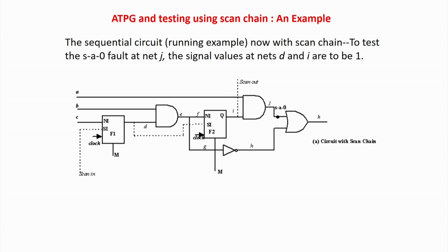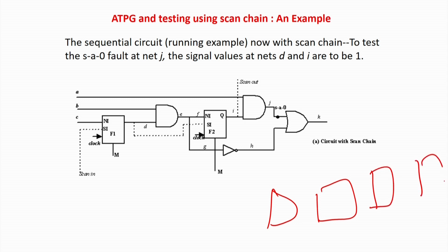Now what I basically have is a single chain like this. These are the chain of flip flops, all connected in a mode. This is one primary input and there will be one output. Now this becomes a shift register. Once it becomes a shift register, if I require the control of 1 0 1 1, you can easily send a sequence of ones and zeros and fill up the shift register chain. So now the problem has been solved in a very simplistic design manner. In VLSI, you always have to remember that complex designs are complex, but the solutions are very simple.